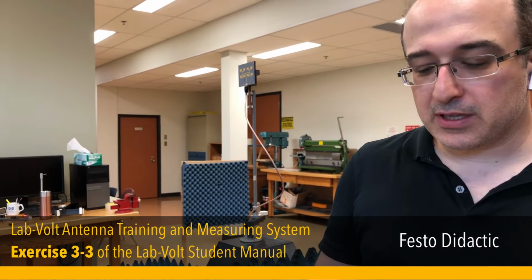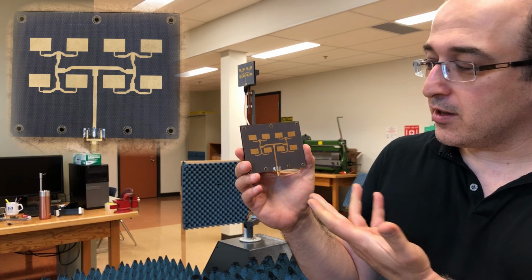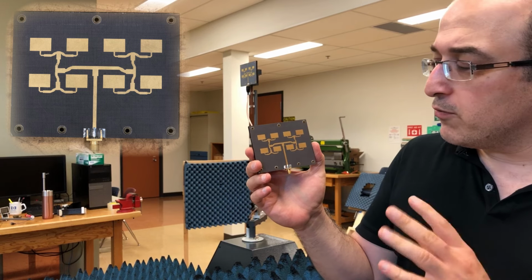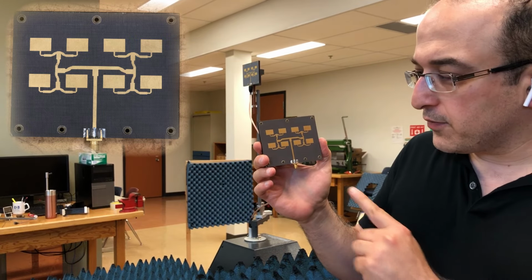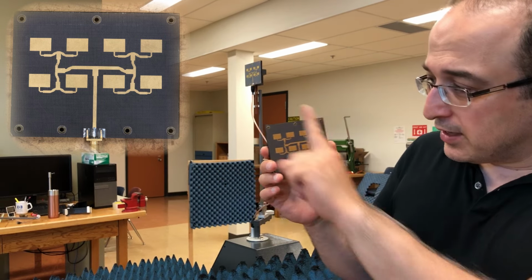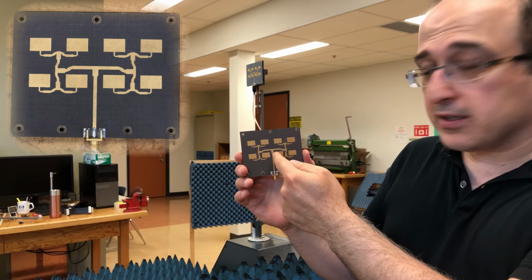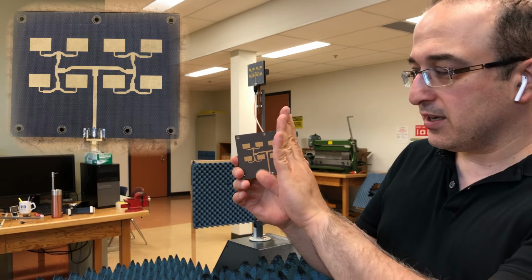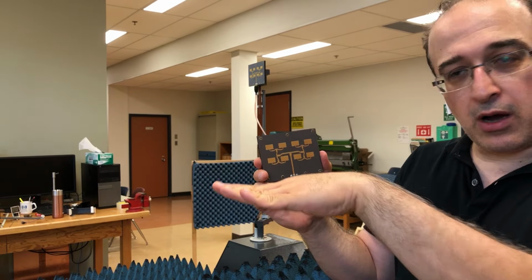Okay, in this lab, we're going to be testing this parallel fed microstrip antenna array. As you know, the other name of this type of feed network is corporate feed. One thing that's important for our measurements here is to note that the electric field of these patch antennas, due to fringing effects, are all vertically polarized. So the electric field is vertically polarized, and the direction of the main beam is broadside, so it's toward you. So if that's the direction of the electric field and the direction of maximum radiation, this is essentially my E plane, and therefore this would be my H plane.